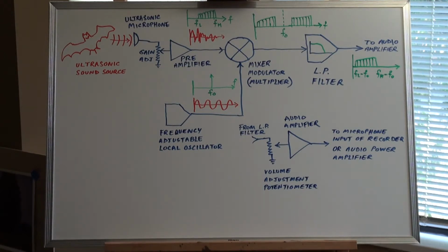Now, you'll see that in these mixer hardware electronics, some of the local oscillator frequency might feed through, which is undesirable, and a lot of the manufacturers of this hardware provide a means of null adjusting the local oscillator, also called the carrier frequency in radio lingo, down to a minimum, or I don't know if it can go down to zero.